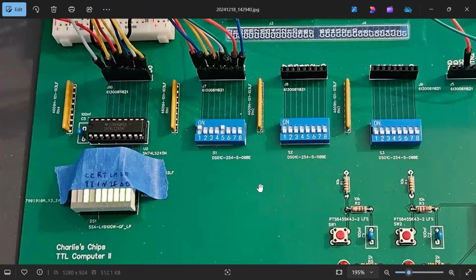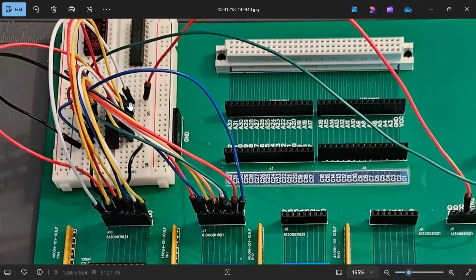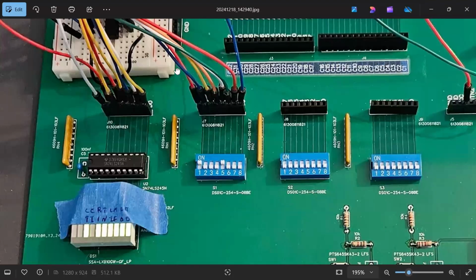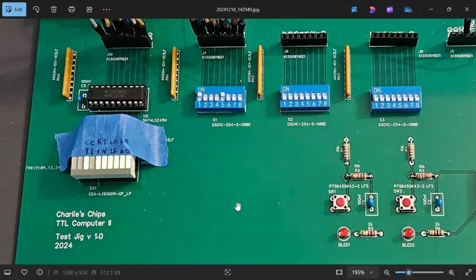A little frustrating, but I'm thinking that was the issue, because again, the clock signal on the D latches in the GAL is not really a configurable element. That's like a hardwired element in the chip. So I couldn't see how the clear signal was affecting the clock, other than that signal bleed over in the breadboards, which apparently is what it was. So yeah, this is a good test.